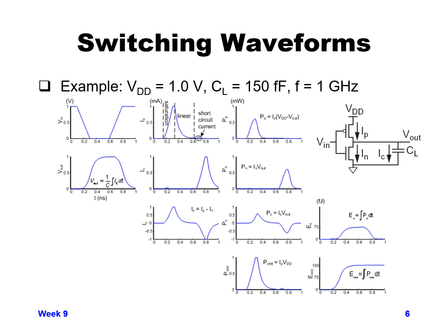At some point though, as the output voltage is charging up, our VDS starts getting smaller than our VGS, and we go from a saturation region to linear region. And you can see those are labeled there. As you go from saturation to linear, your current hits its peak and starts going back down, because as V out keeps getting closer and closer to VDD, there's less and less current in the linear region, and so you can see the current is tailing off at an exponential rate, decaying toward 0 current.